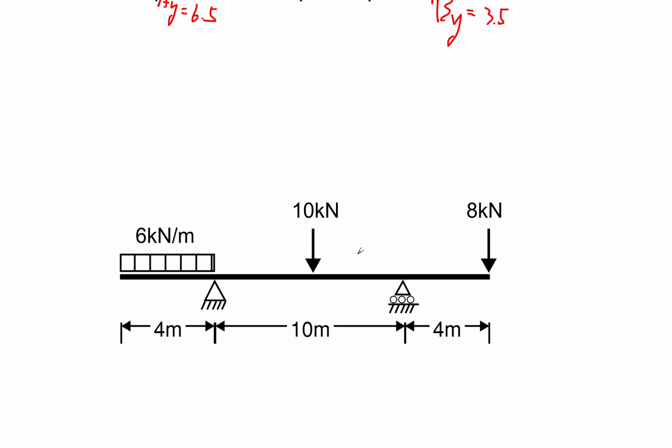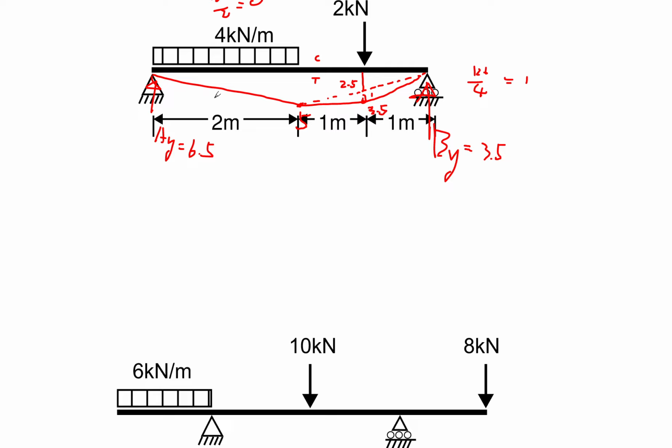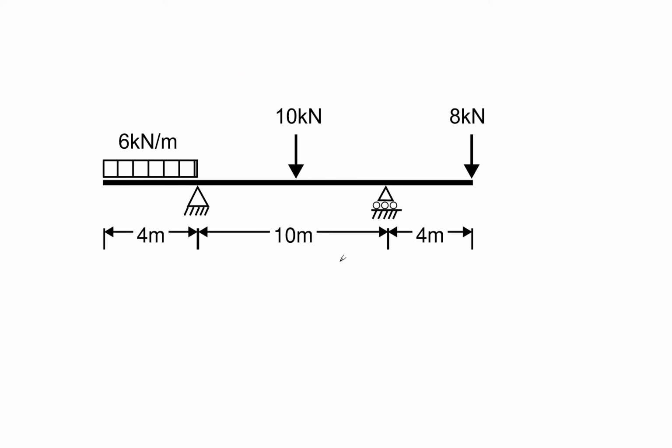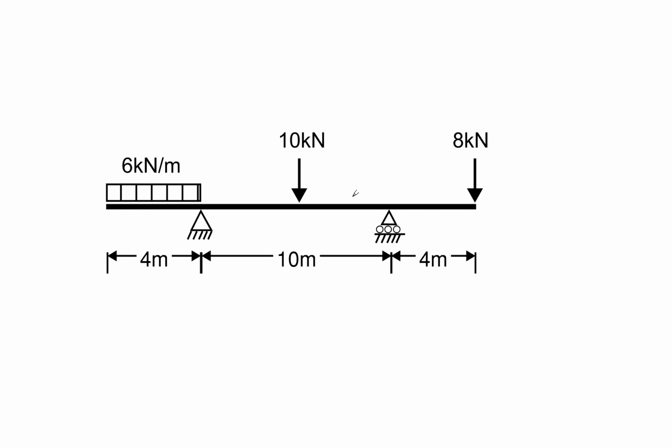For this job here, we don't need to do the reactions. We can just draw using the graph method, and based on the bending moment diagrams, we can derive the reactions. So let's start from the cantilever end. Let's start from this end here.